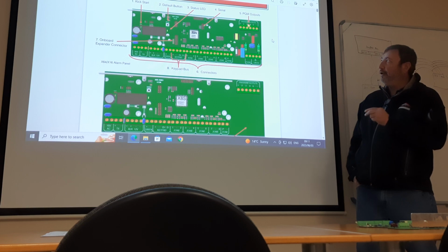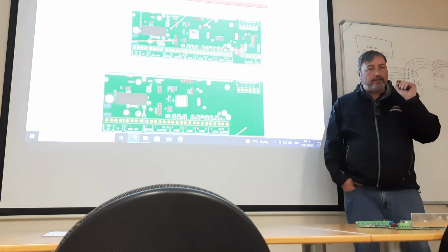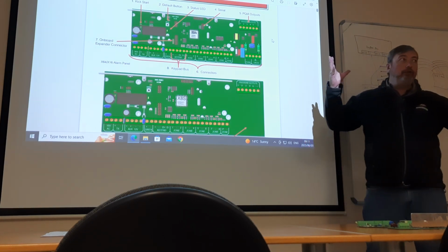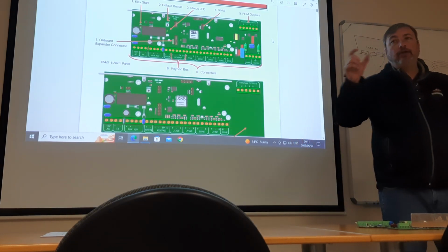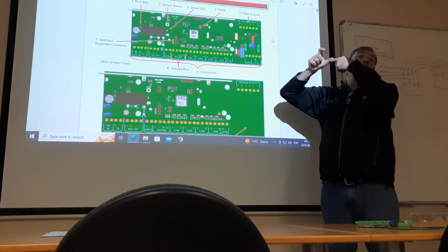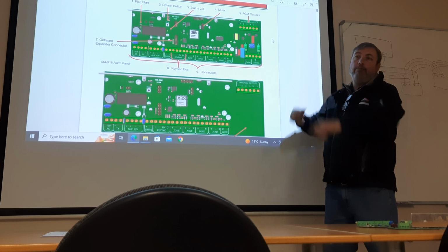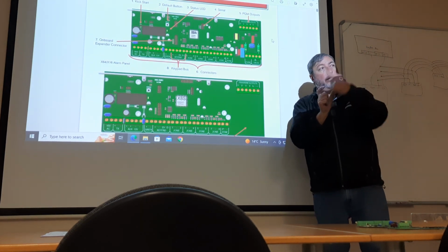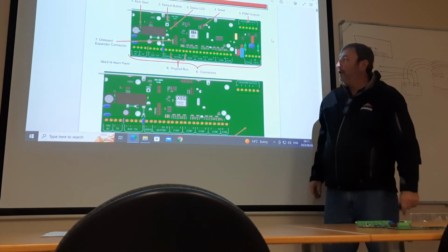I think output number 3 you can use. That one doesn't send out pulses. That one you can latch. So that one you will actually use if you want to switch on your floodlights or whatever. But remember, you just need to have a 220 volt relay on your live wire that goes to the main panel. This one is basically just to switch on the main 220 volt relay to switch on your floodlights.